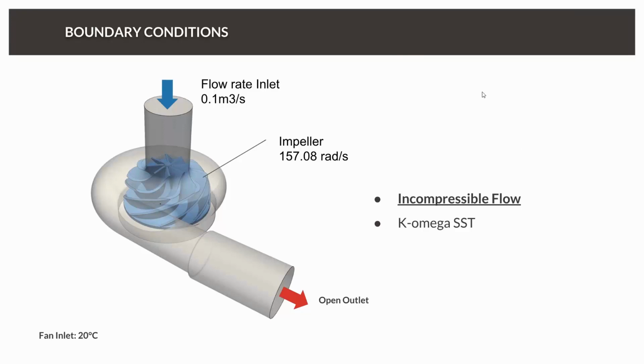And let's talk about some important things and some questions which are raised often. First of all, a lot of you maybe think, oh, this geometry looks a little different than what I'm using, and you're right. A very important step of a simulation is actually to prepare your geometry, to make it ready for use. And just think about it. What we are interested in is the flow inside the pump, so the domain which is between the impeller and the housing.